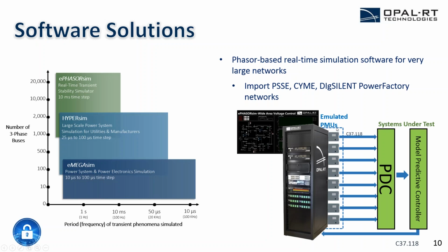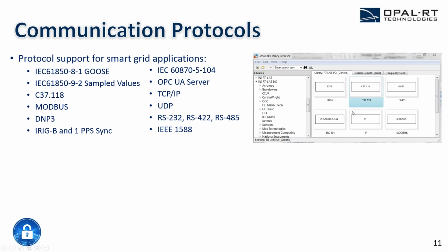PMUs with the system. One of the projects we're working on in-house is to create such a setup where we're using the IEEE 39 bus system as a base. We're connecting this to a model predictive controller via a PDC, and these, I should note, are all real devices. All this is done at a software level here, so there's no hardware used at the lower level.